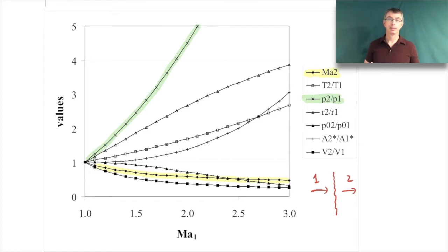It's just a huge amount of pressure hitting your body all of a sudden. And you can see that if the Mach number of the shock wave is larger and larger, that pressure difference grows, right? So the more energetic the explosion, the faster the shock wave propagates, and then the larger the pressure difference and the more damage it can do. So when I say a strong shock wave, what I mean is a shock wave that's traveling at faster speeds and has a larger pressure difference across it. So you can get these really significant pressure rises across a shock wave, and they can cause considerable damage.